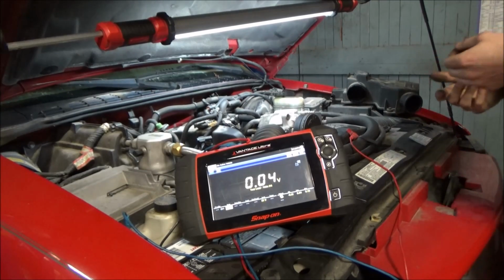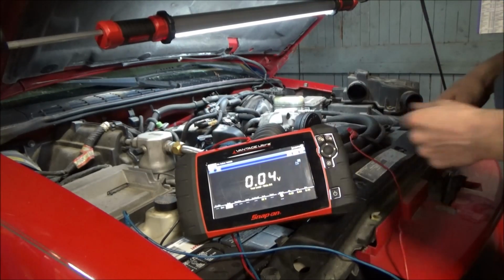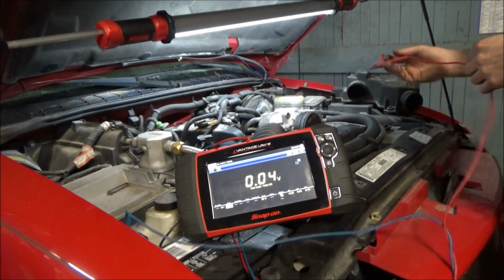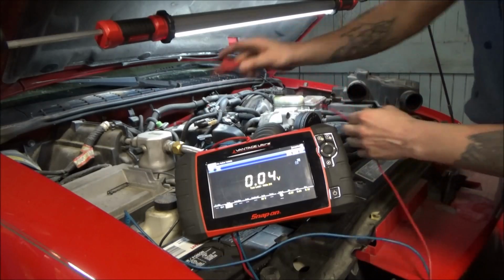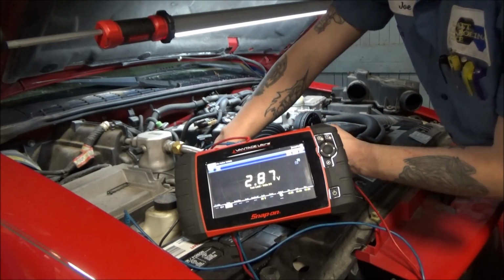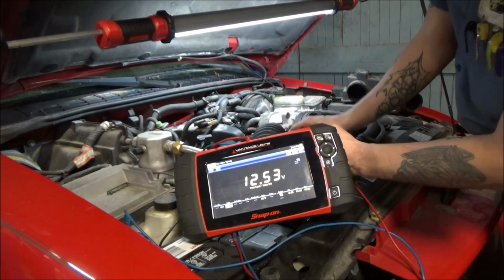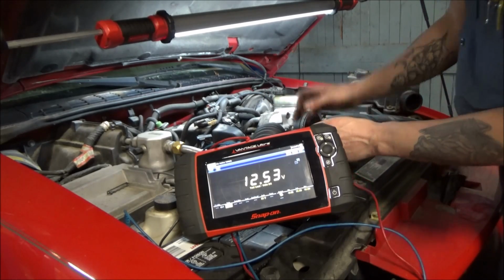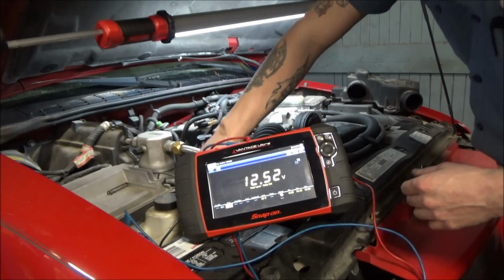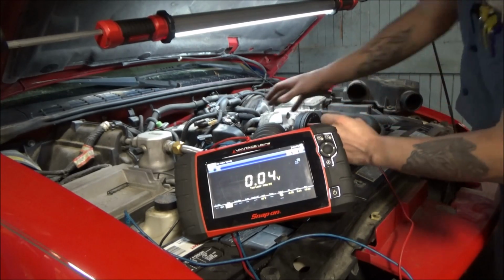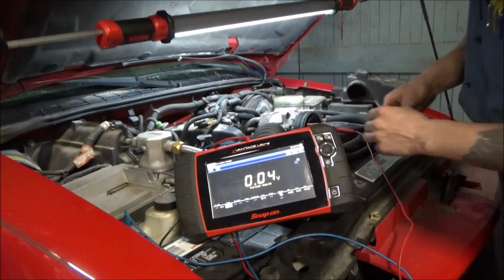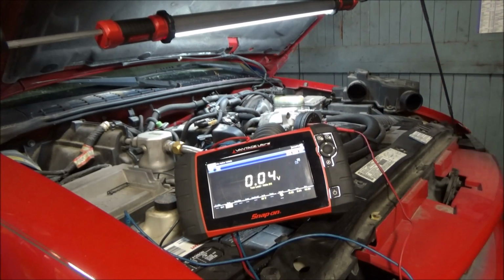Alrighty, guys, so for simplicity's sake, I've got you guys focused in on the digital multimeter. We're using the Vantage here. So I've got my black lead going to battery negative. I'm just going to touch my red lead onto battery positive to ensure we have a good ground for our meter. We're reading 12.53 volts, so that's looking good. So we're going to start attacking this throttle position sensor at this point, and you guys aren't going to be able to see me testing the sensor too well from your location, but you will be able to see the meter. And I'm going to definitely walk you guys through what wire I'm hooked into and all that good stuff.